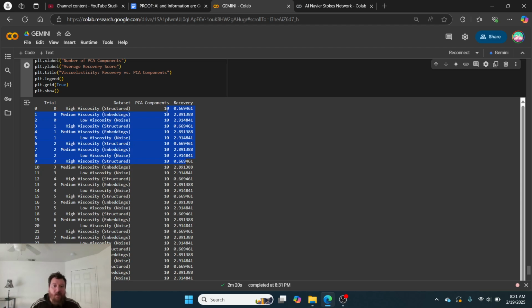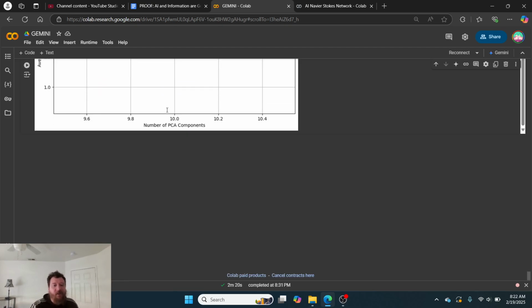What this shows is that, especially within the high viscosity data sets, there's recoverability, and a lot of recoverability, like above 50% recoverability. So it's not a solid, right? It's more like a non-Newtonian liquid between a solid and a liquid state, where you could blow out the wall and it would crack, and it would probably put a hole in the wall, but the hole could heal itself, right? And the crack would heal itself, and you'd have some sort of healing effect, but not 100%. Like, it wouldn't fully recover from it. It would recover like 66% in the high viscosity test, essentially, right? It's kind of what you get from that.